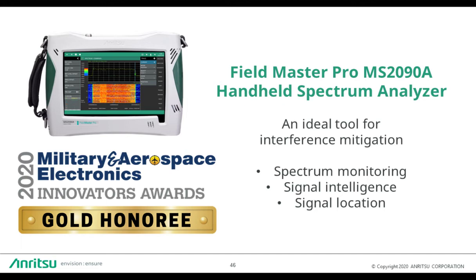I guess I didn't go into a lot of detail there. POI stands for probability of intercept, and it's a general term to help define the performance of a real-time spectrum analyzer. The reason it's important is, as I mentioned before with an RTSA, you are always sampling and then processing in the background. But even when you're sampling, you do have some windowing effects, some filtering that's happening in the analyzer.